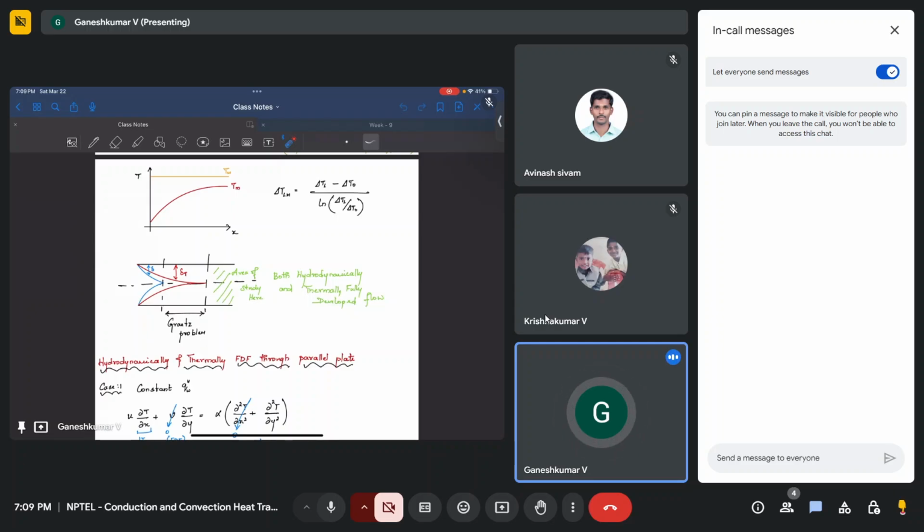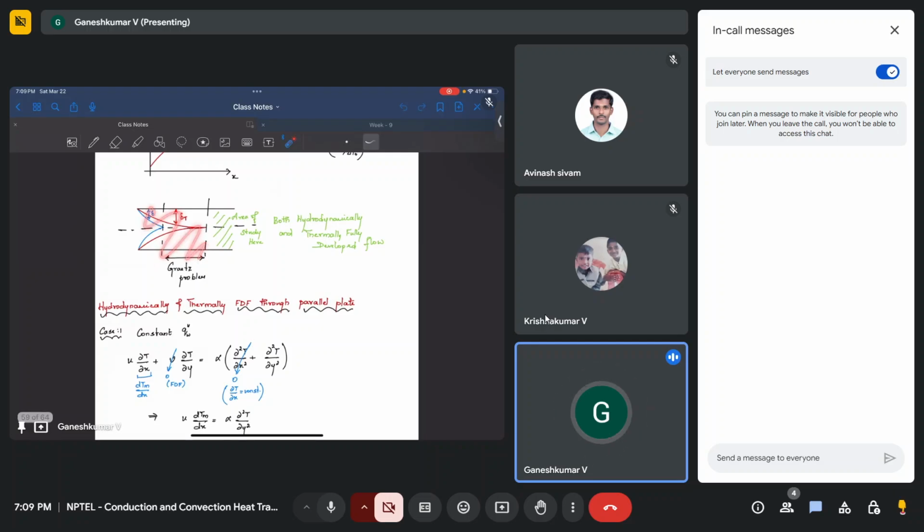We are going to go forward and study how to find the convective heat transfer coefficient, and eventually the Nusselt number, for problems of forced convection inside a parallel plate or pipe. We are going to ignore this initial part, especially. We call this the Graetz problem, where once the hydrodynamic boundary layer is developed, the thermal boundary layer is still developing. But we are not going to study any of this. We are going to study only hydrodynamically and thermally fully developed flow.